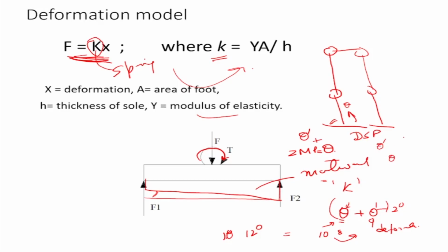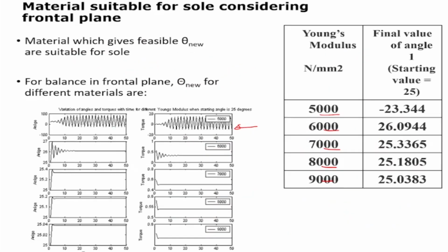So what is happening? There is some kind of oscillation, and this is the oscillation shown here. Let me come to the joint angle again. I have moved the joint angle by 10 degrees. There is a motor there, but because it is soft, it has not moved by 10 degrees, it has moved by 12 degrees. So I need to make the correction and bring it back to 10 degrees again. I reduce this one to 8 degrees, and now it becomes 10 degrees, or somewhere a little less or a little more than 10. So there is some kind of oscillation going on, and you can see the oscillation that is there.